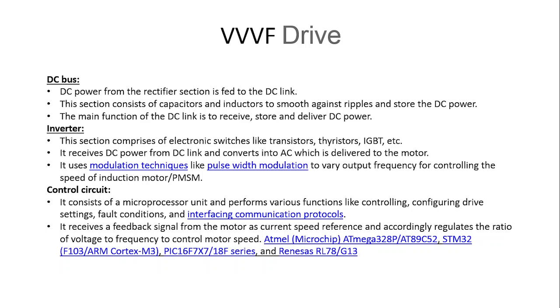The control unit basically provides the firing pulses for the rectifier and the inverter unit, configures the drive settings, receives the feedback signal from the motor, and regulates the voltage and frequency accordingly to change the speed of the motor.